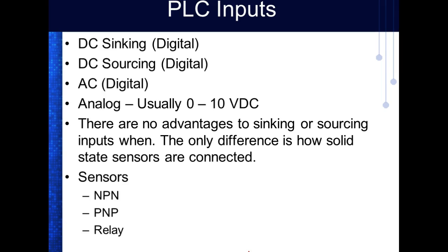So I think the solid state limit switch that we have, if you take the sensors class, I think we're teaching that. I'm teaching that next. Yeah, so this is the solid state limit switch, and that's AC. But if you look at the panel, it'll tell you the voltage that it's supposed to run off of. So that's an AC sensor right there.